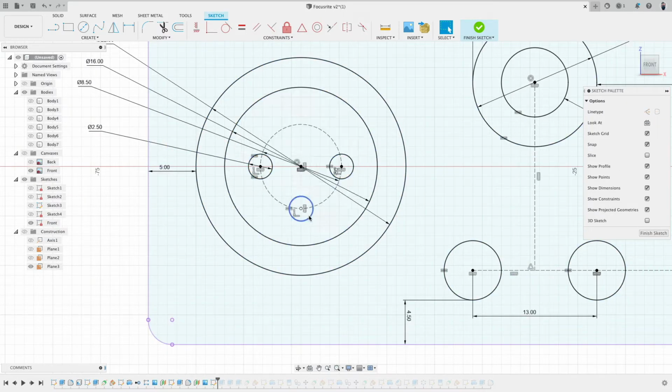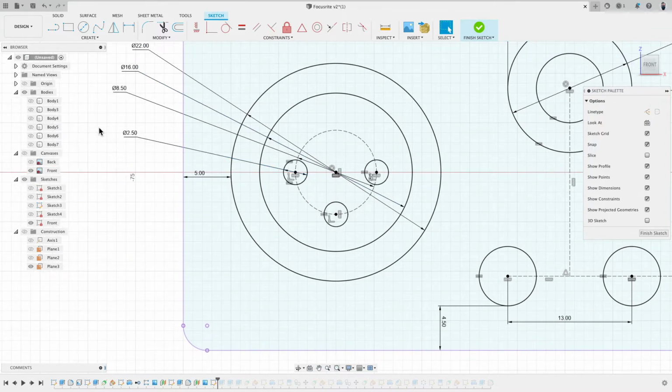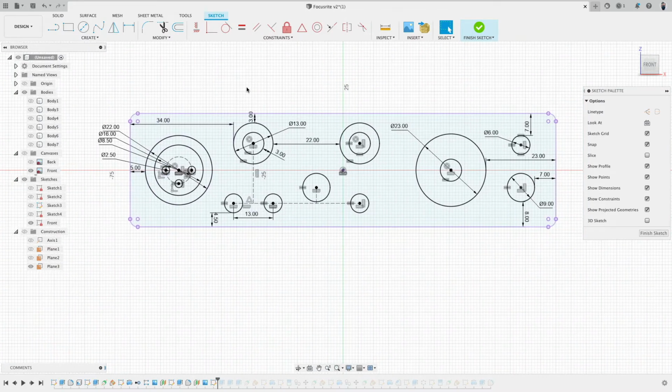And then these other two, they got the equal constraint. So when I change this to 3, you see they all change. Again, this is all simply about an effective way of setting everything up and creating these constraints. I also have here this button, or this circle, vertically aligned to there. This is just one way to do this. To get exactly the same results, you could use a different method. So this is really important to understand, how flexible this system actually is.